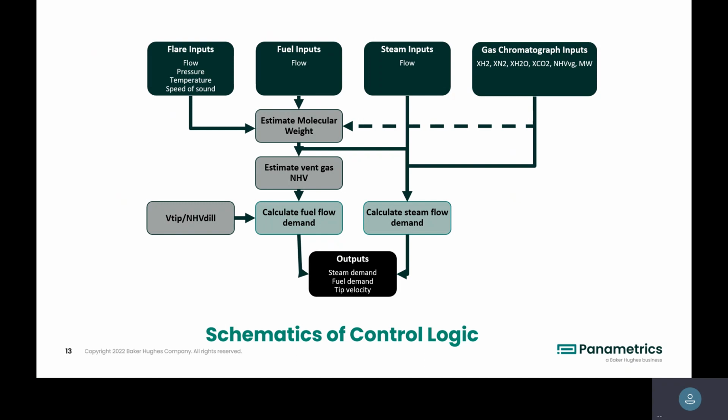So Jeff, Paul, basically Flare.IQ can be self-sufficient. The only thing is when it comes to reporting the NHV value, based on the EPA, they take the GC or mass spec or calorimeter. Those are the three. As a manufacturer of Flare.IQ, historically we don't push this technology to be accepted by TCEQ or EPA or wherever.